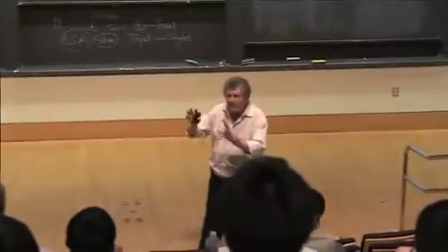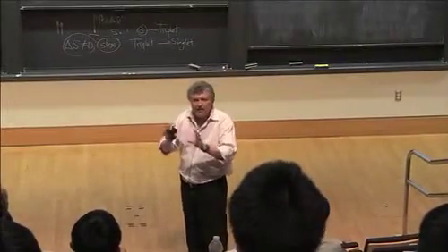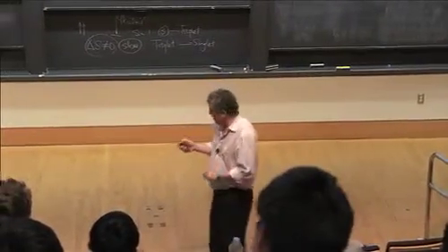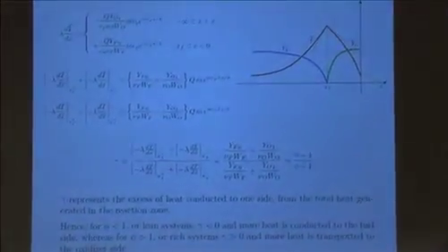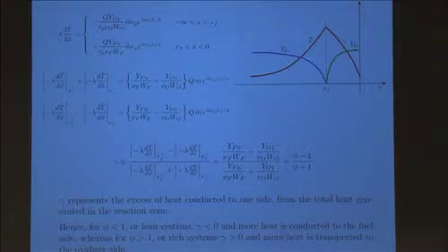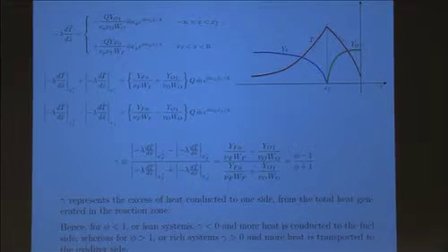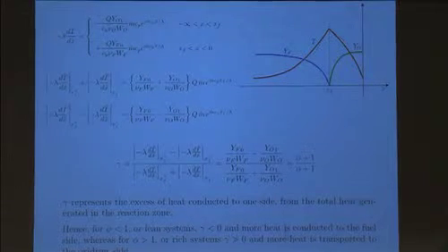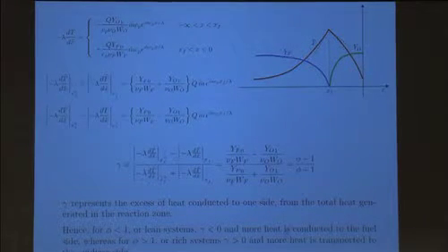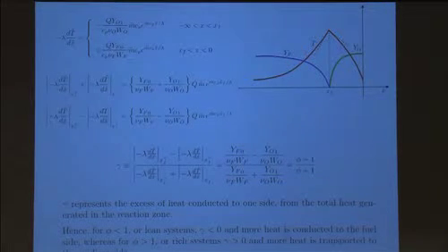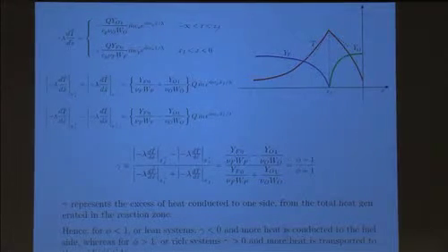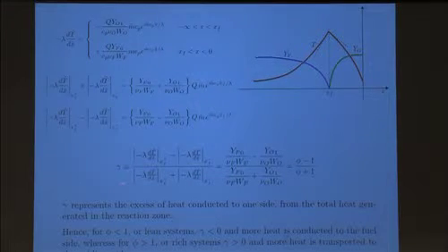Because you see, when the Lewis number differs from 1, then diffusion can, in fact, vary those things a little bit. So anyway, what it tells you is this. If phi is less than 1, which corresponds to a lean system, meaning that the supply of fuel relative to that of oxidizer is less than the stoichiometric proportion, right? And so if phi is less than 1, which I interpret as a lean system, then clearly gamma is negative.